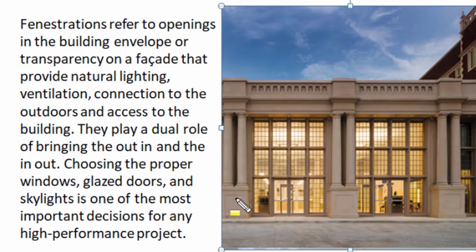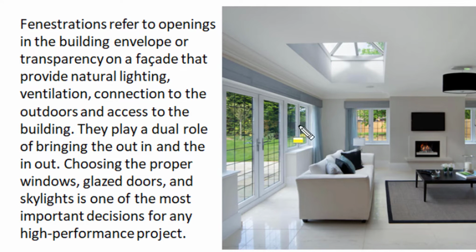Fenestration refers to openings in the building envelope or transparency on facades that provide natural lighting, ventilation, connection to outdoor and access to the building. This fenestration plays a dual role of bringing the out to in and in to out. So the in-out in building from external sides takes place through fenestration. Choosing the proper window, doors or skylight is one of the most important decisions for any energy efficient, high performing green building project.